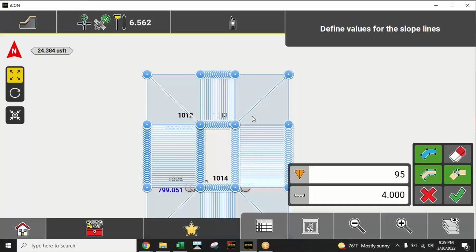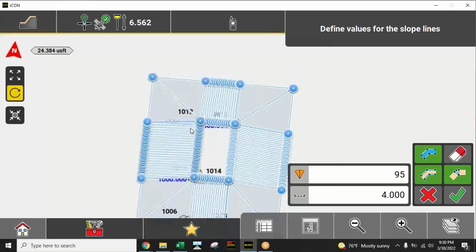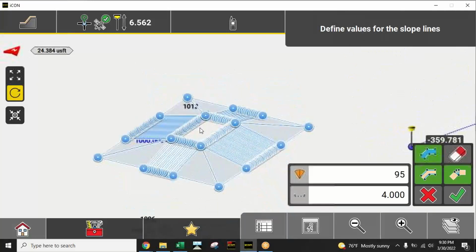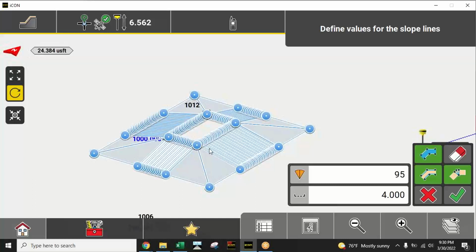If this is actually a curve, of course we got a 90 degrees right here, but if it comes up and it goes around a curve around through here, it's going to put a whole bunch of additional break lines through there, kind of like this one right here. So anyhow, all those got a particular use, and you can kind of see how things are shaping up, coming straight off here at whatever we had for our slope, 25%, 25%, and it spits one out here on your diagonal on your corner. So you got your corner grades right there.